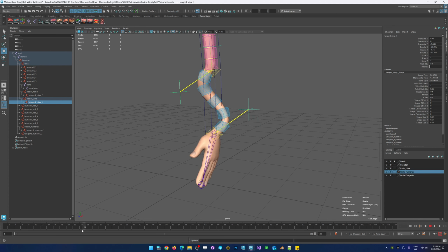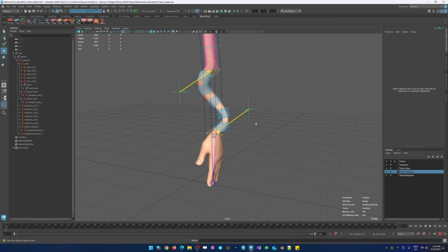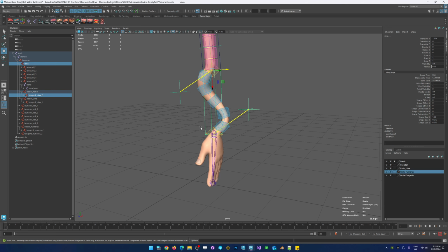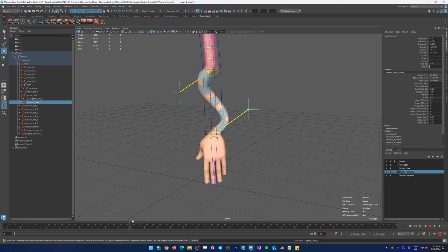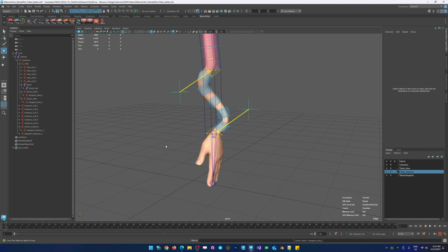As it spins, first let's grab this guy and make sure it's not connected to the hand or to this object. I'm just going to make it a child of this bone. Now, see, it stays, it has the shape, and we can do something that is very difficult to do normally. If you were using Euler values, this would break instantly. So let me just undo so we can get back to the original shape.